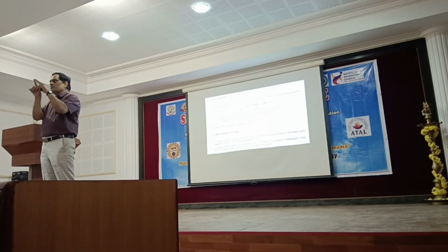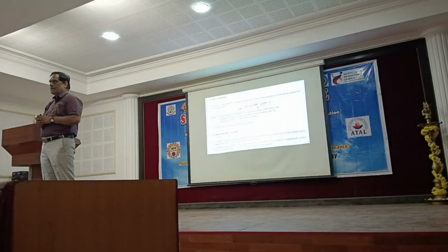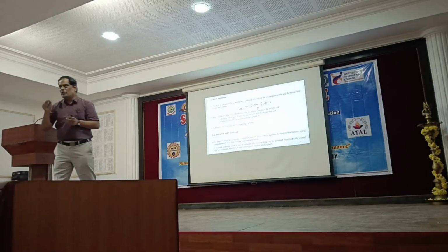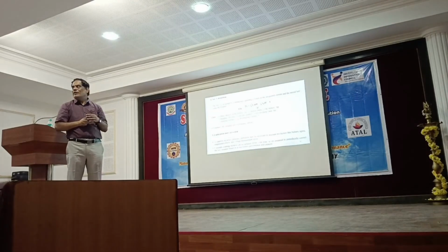I already mentioned spatial and temporal evolution. In a given space, how much mass of the active material can I actually put in? When I say active material, I mean cathode material, anode material. So I should know how much current can flow per unit area. Spatially, I take a rectangular sheet. How the ions are moving as a function of time and space depends upon how much material I have put into a particular space. That's why I talk about current density, the amount of current flowing per unit area.